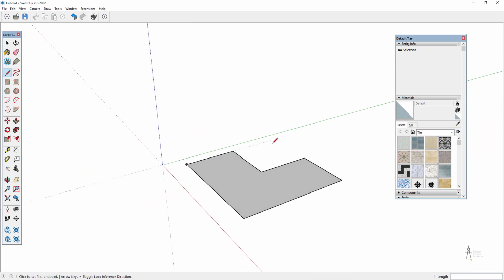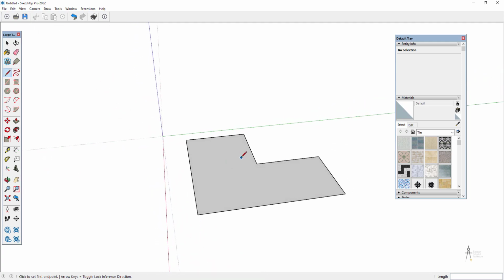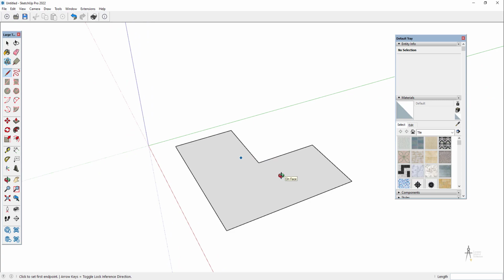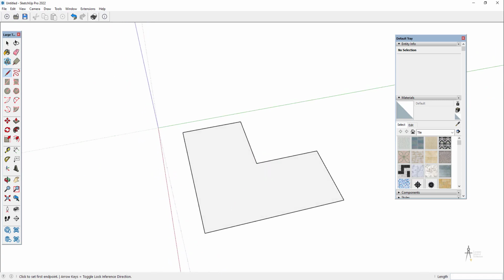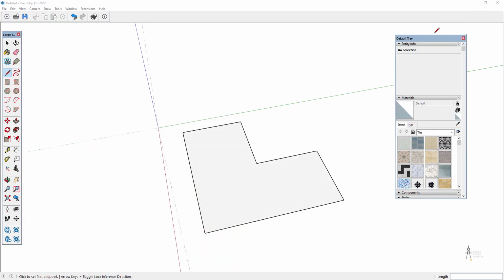Okay, so you probably think now it's time to extrude. What I'm going to do is I'm going to find my offset tool, but I have to find out how wide the wall is. Okay, because I want to extrude the wall directly, so I'm going to come here, and here if I know it's 5 and I know that this is 450, I know it's half a meter, so it's 25 centimeters each wall.